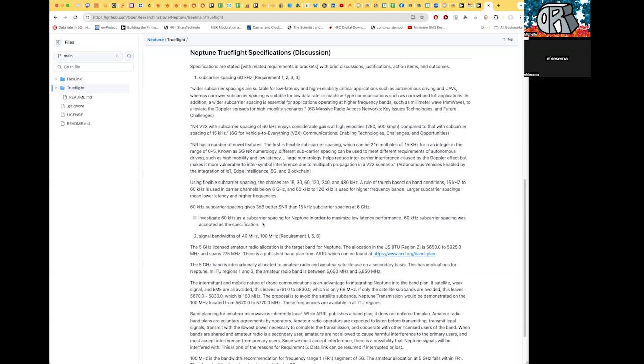And you know what? In talking about this issue, I found there actually is some really cool stuff that you can do with OFDM. When we talk about signal bandwidths and specs that support low latency and also reliability, there are some really neat things you can do with OFDM. You can add subcarriers. When conditions are great, you can sprawl out and add subcarriers. And when things are not so great, you can pull back.